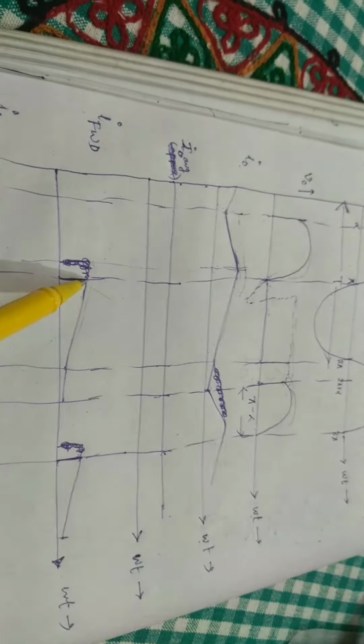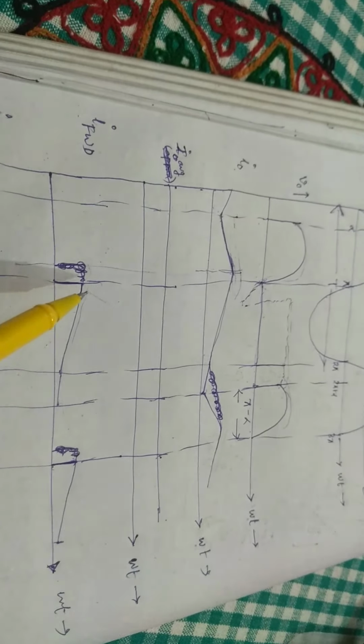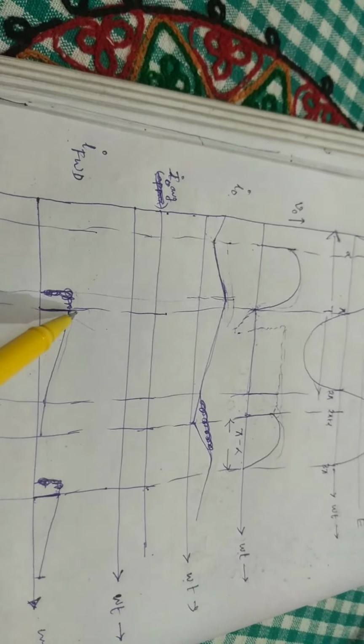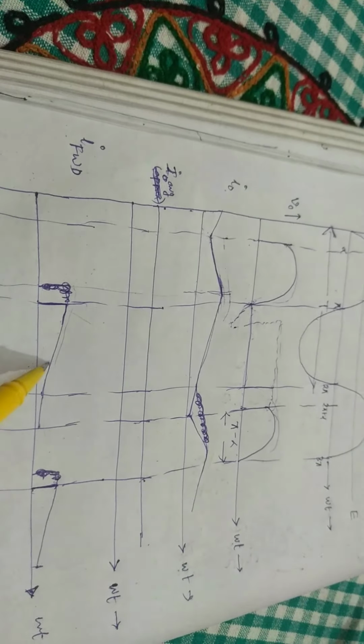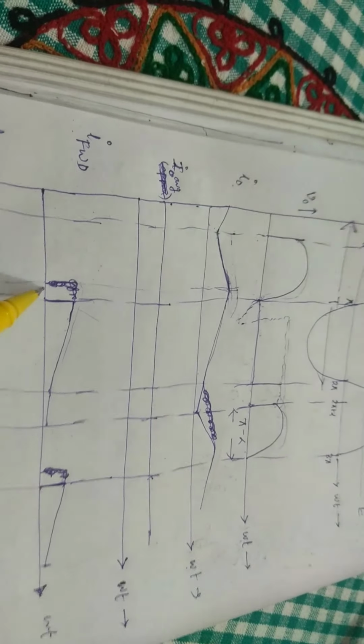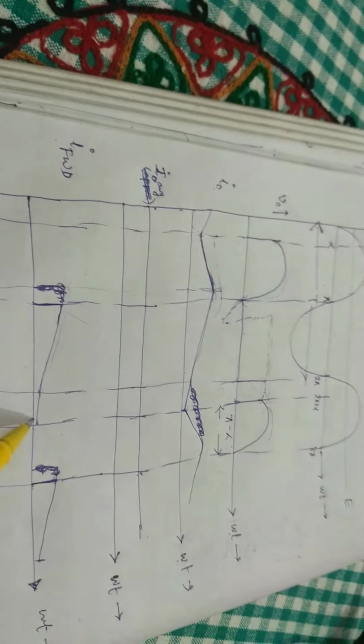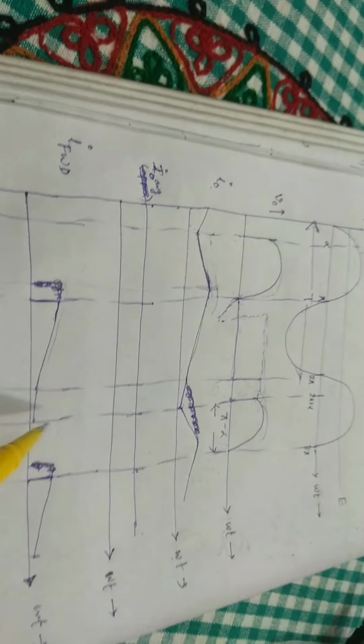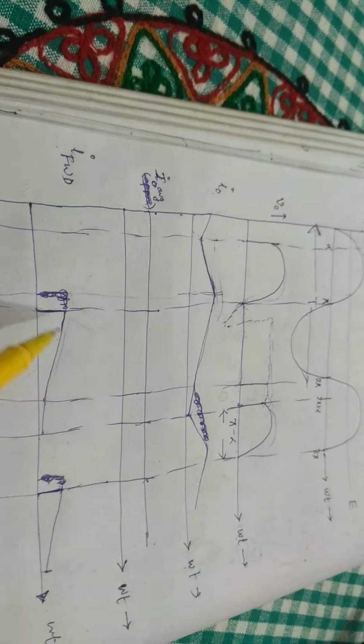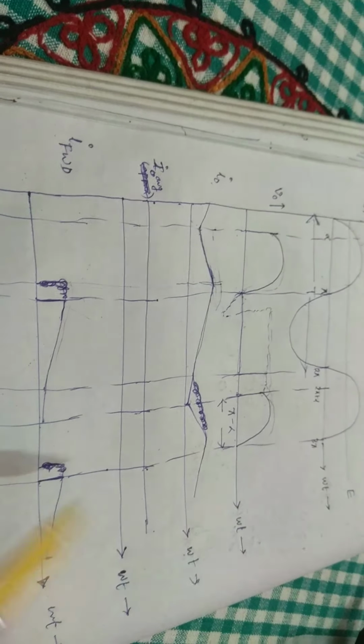Now if it was discontinuous conduction mode, then this freewheeling current could have decayed to 0 at any instant between pi and 2 pi plus alpha, but because we have considered continuous conduction mode, I have shown this to be continuous current.